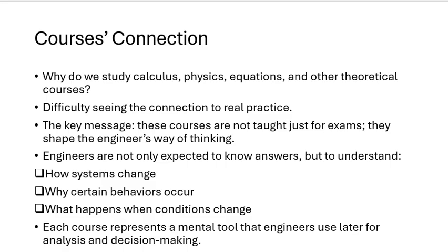The science told me what is happening, why it is happening, and when it happens, what will happen around it. So when I know, then I can use it or do something about it. If I don't know what will happen when cement reacts with water, what is the result? Then all my concrete will start having cracks. It will fade. Got my point? So just by missing this one small point, you can destroy your entire building. The reason is you didn't put water, you didn't try to decrease the temperature after the concrete became hard. You didn't consider the type of reaction. Got it? Clear or not?